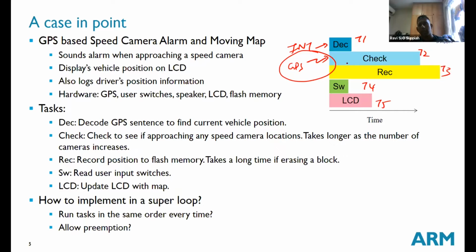Correct. And if, let's say, other loops can still carry on, I can design other loops to carry on even though I don't have GPS data. All right. I can still be updating the LCD. I can still be monitoring the switches and so on. Okay. So if you look back to this first example, now with all the knowledge you've gained from your RTOS, you now see that I could have done this in a lot more elegant way.